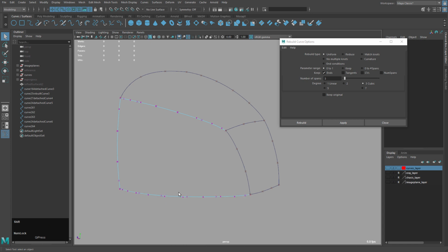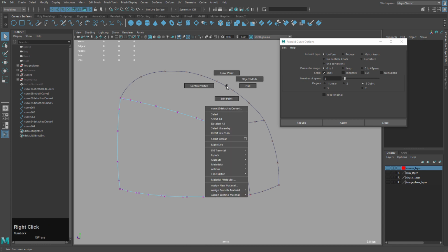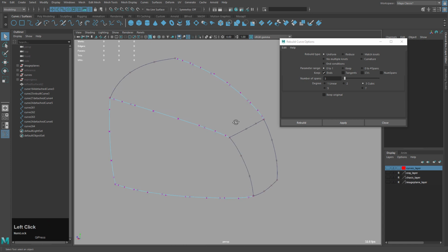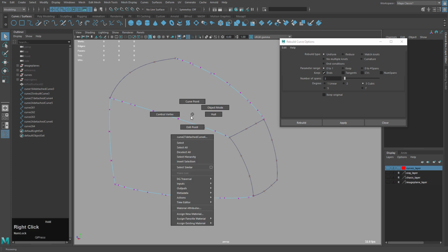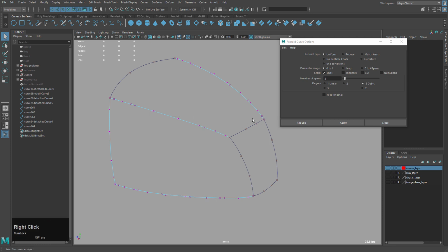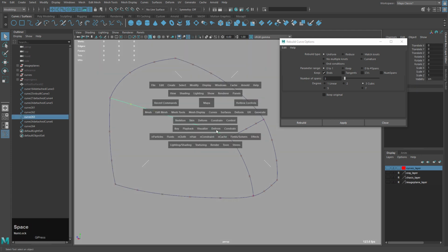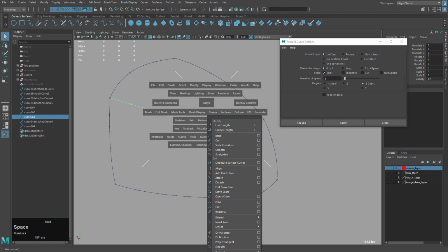and you can check it for all the rest of the curves. It's not completely necessary, but you may have issues when you're doing lofts and stuff, or bi-rails, so this will just make sure you don't have any issues. You can see the U is here and that U is over there. This one's here, so we just need to select this one and reverse this direction.